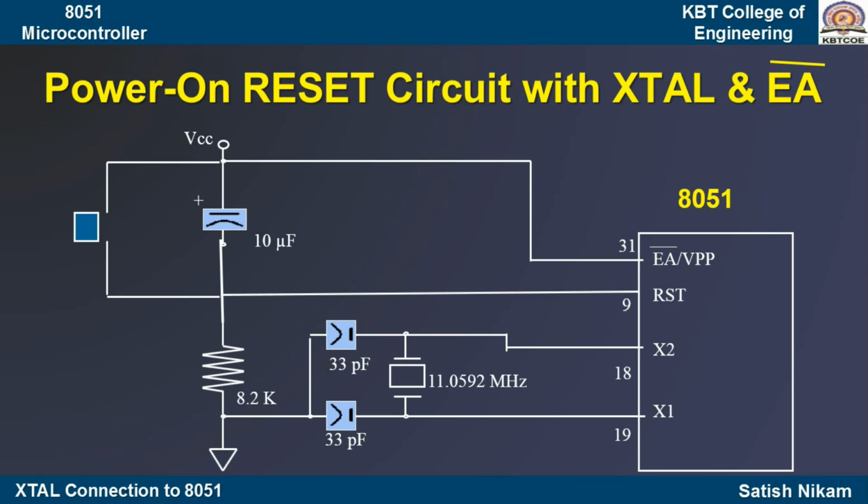We can reset the microcontroller in between. If you want to use it, suppose the program which is going on and I want to reset my microcontroller. So what I have to do? Intentionally I have to connect this reset pin to VCC. So I will use here one push button. So you are having one push button, you can design a one push button, so that when this push button it is get pressed, the VCC, this my reset pin is directly get connected to VCC, and you have to press that push button for 2 machine cycle.